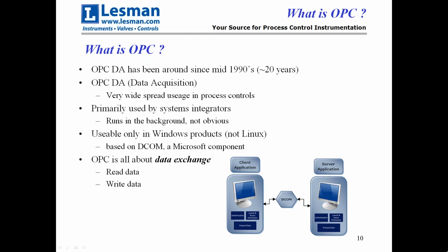The people that think they're just using Allen Bradley, for instance, when they buy Allen Bradley's RSView or FactoryTalk HMI package, actually that comes bundled with, I don't know whose it is, but it comes bundled with an OPC server. Allen Bradley licensed somebody's OPC server. So the people that just think they're using Allen Bradley PLCs and Allen Bradley HMIs are actually using OPC for the things to talk back and forth together.